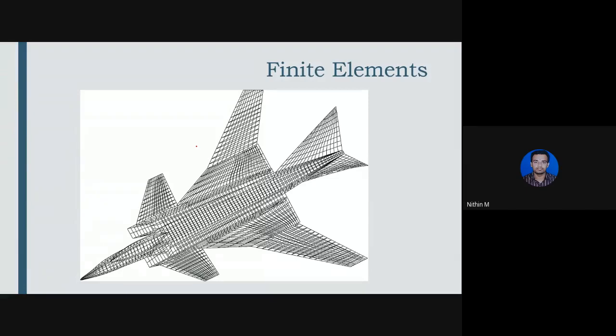Essentially how do we measure strength? Strength is measured in terms of Young's modulus in most of the cases. In some cases, it is even measured in terms of yield strength or ultimate strength based on the type of the material. So this value, let us say yield strength of the material divided by the weight of the material for that particular strength, is extremely high in case of composite materials. Because there we will be making use of a matrix phase and a reinforcement phase. Basically, the objective is to reduce weight.